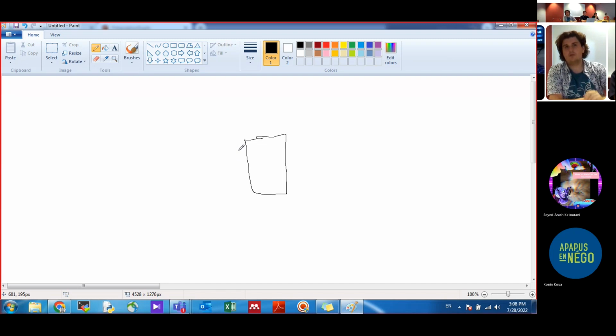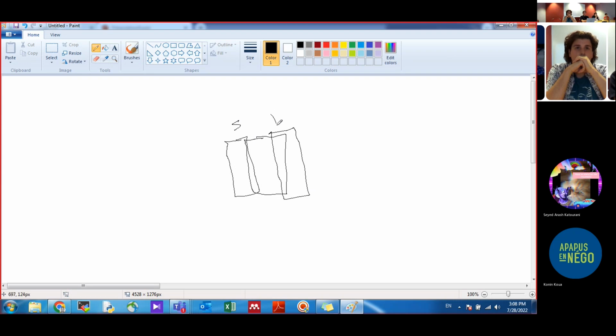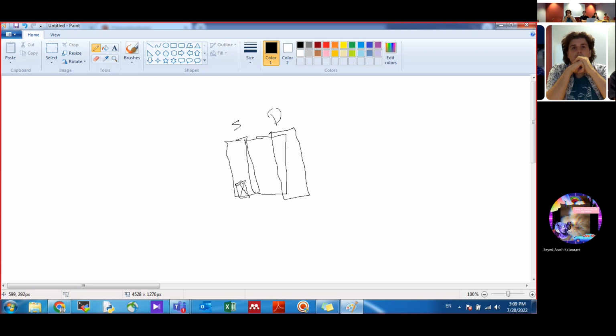Okay, so this is the gate, this is one of the source or drain, and this is the source or drain. So use one via. The vias always depend on the length of the whole thing. Normally I just take a rectangle via and put it all over the source and all over the drain.